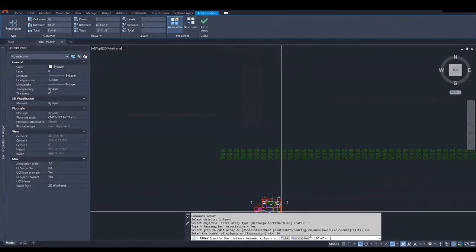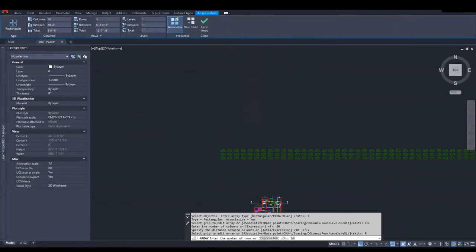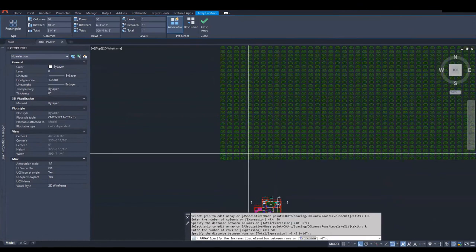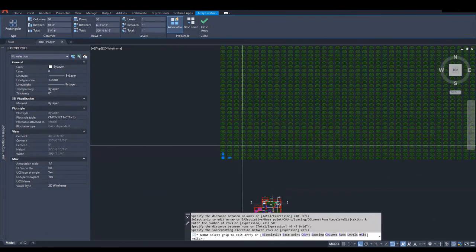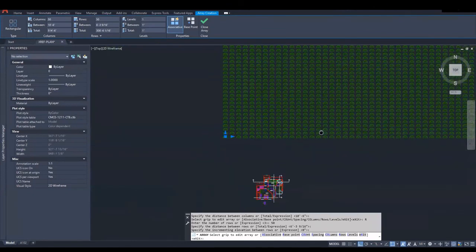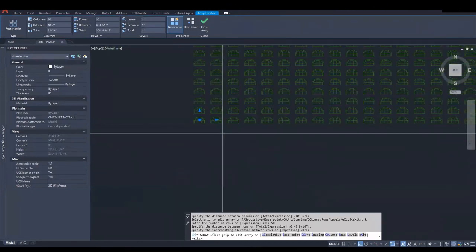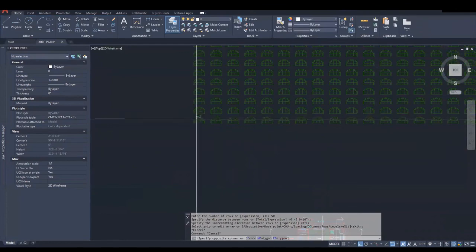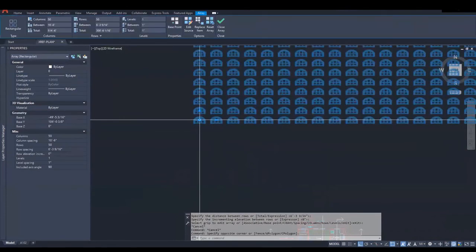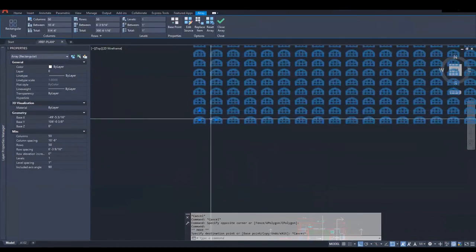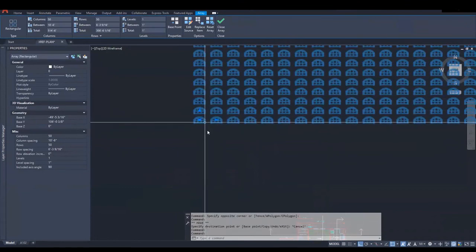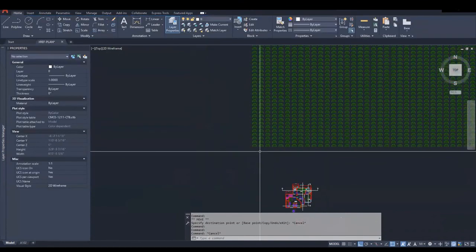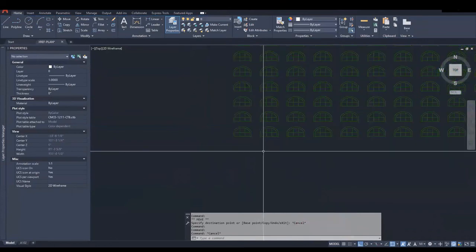And just as an aside, as a sort of separate little discussion, the array function, which I'm using here, is basically a way of copying an object multiple times fairly easily. So if this was, let's say, a parking lot or an auditorium, a concert hall, a stadium where there's a lot of repetition in terms of the seats or the layouts and things like that, I can use an array to be able to unilaterally set the number of rows and columns and copy the same object.